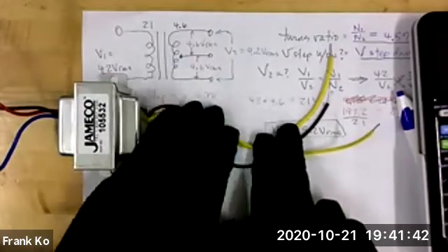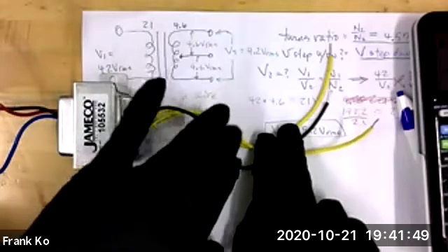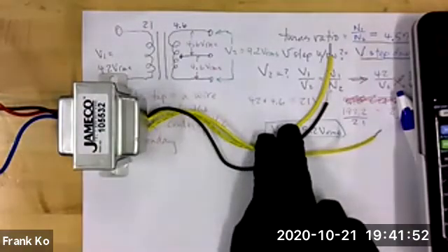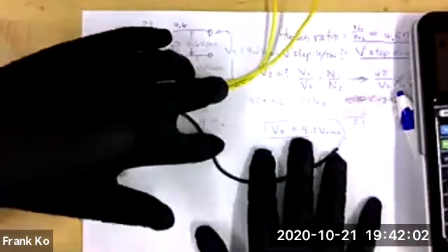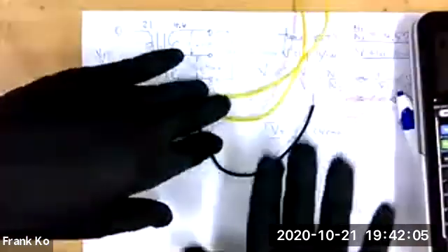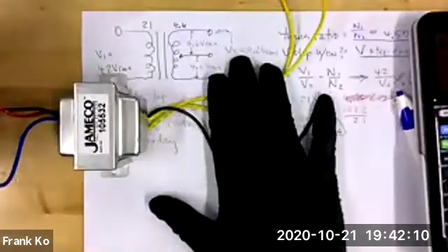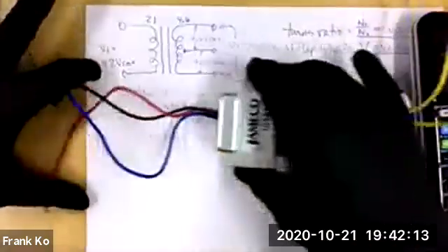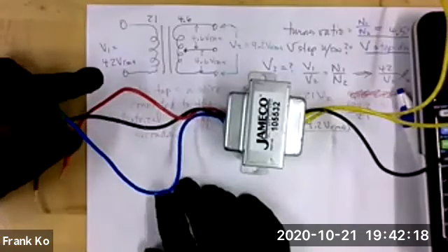We're going to designate this side as being our secondary. Do all of your transformers have a pair of yellow wires and a single black wire on one side? No. Okay, what are your matched colors? 2 white, 1 black? Fine. So you have 2 white wires and 1 black wire. You will go ahead and use that set as being your secondary. So far, so good? What are your colors on the other side? Yellow, black, and red.